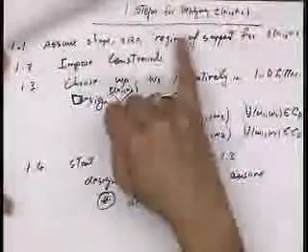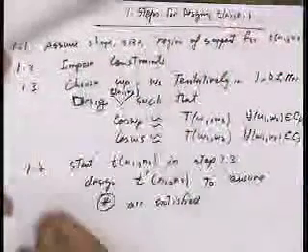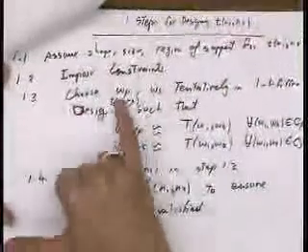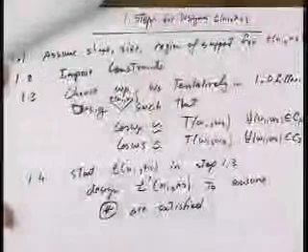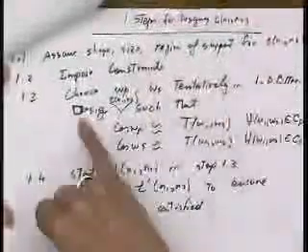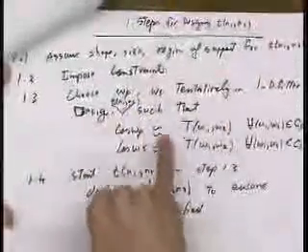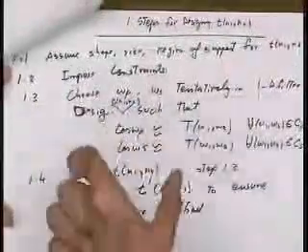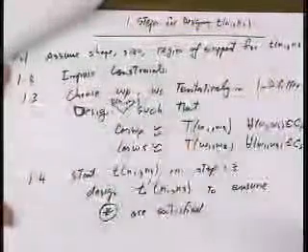You assume some sort of a shape and size, you impose some constraint, and then you tentatively choose omega p and omega s for your one-dimensional filter. Based on that tentative assumption, design T such that these conditions are satisfied. We come up with an error function, E sub p and E sub s, and then solve the least squares problems, which involve solving linear systems of equations.